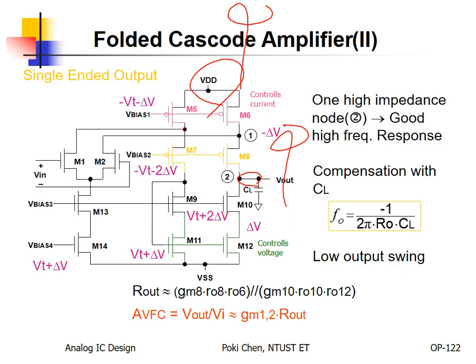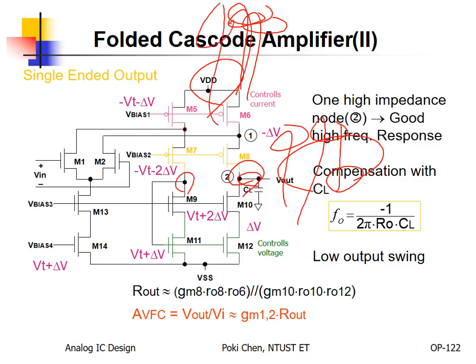That is your case. I don't think you have any kind of circuit where if you increase the VDD, then the output will be decreased, unless you have a very special design for compensation. Otherwise, the higher VDD usually means higher output. That's it. Anyhow, the positive output is increased. How about the negative? The same. The higher VDD, the higher output.